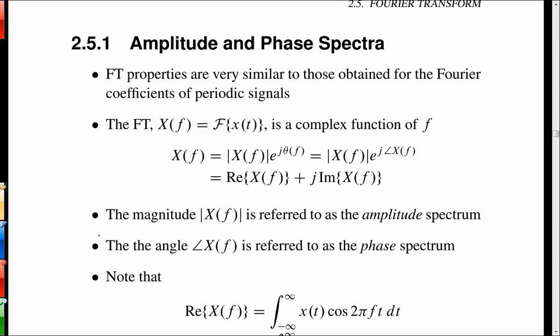So once you are into the frequency domain, you have a continuous spectral representation for the signal, whereas the periodic signal is not a continuous spectral representation. It just has spectral lines in it at the harmonics. And we know that's the case because that's what Fourier series is all about. It says you just need to have a spectral component at harmonics, not everywhere. But when you have a single isolated pulse, it becomes a continuous spectrum.